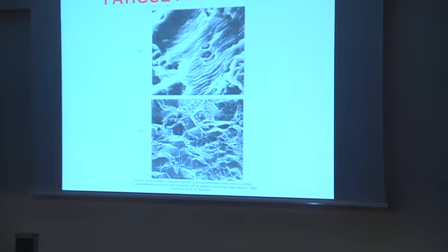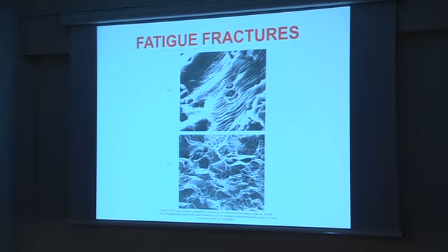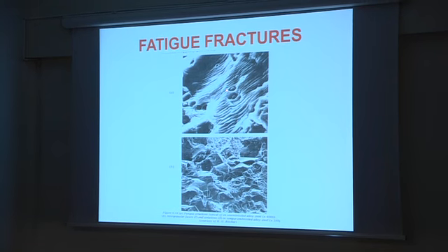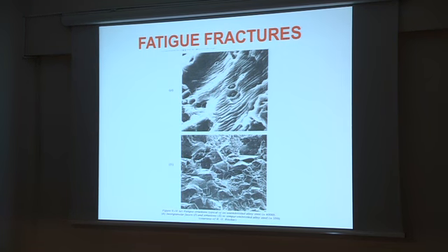Let us look at the upper figure. You see striations, but think of these microvoid nucleation around spherical particles. Let us consider that before fracture by fatigue or by something else, you have a crack.